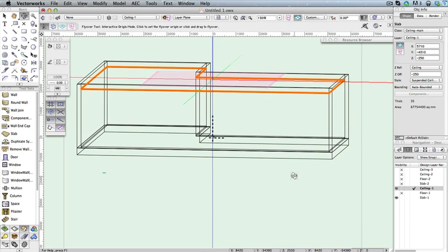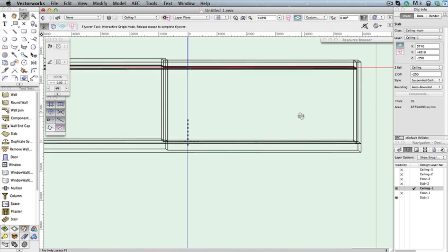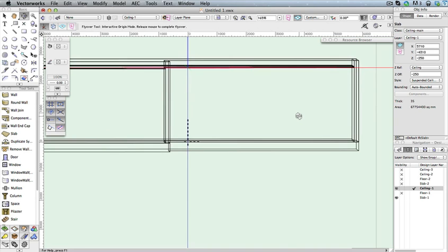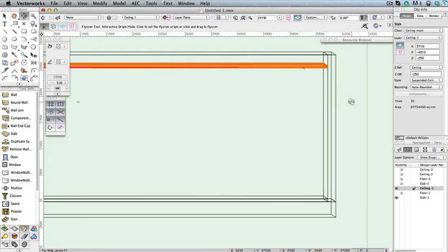Remember, the top of the walls are bound to the ceiling design layer. So, you should notice that the bottom surface component of the ceiling slab, which was selected as the datum, is 250 millimeters below the top of the walls, leaving space for things like lighting fixtures or ductwork before reaching the slab from the stories above. At this point, we've created the first story of our model.